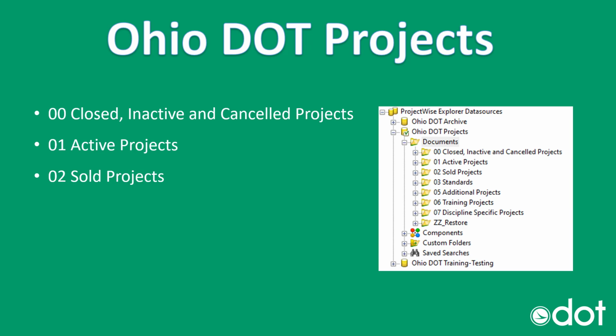The 03 standards folder is where all the ODOT standards are located. So this pertains to the help documents, some templates, and some other things like cells are located. Now, the Managed Workspace within ProjectWise pulls this data from this standards folder so that all your work sets or PID folders can pull these so that all your projects have the most current ODOT standard. So when you go to design your projects, they are up to date.